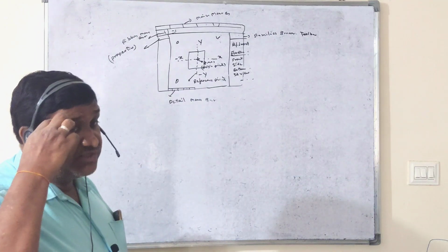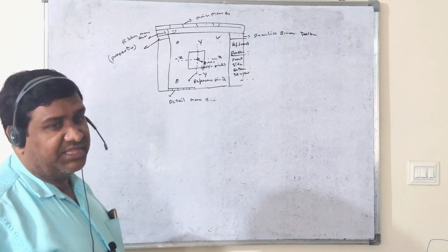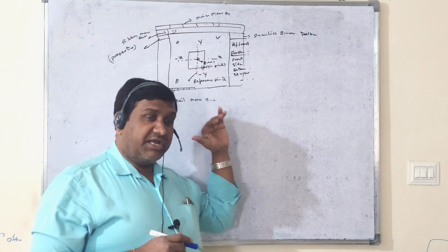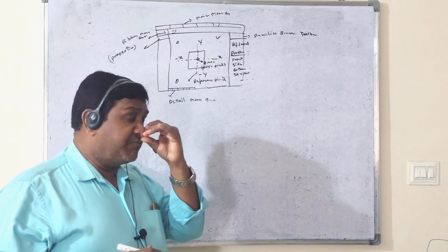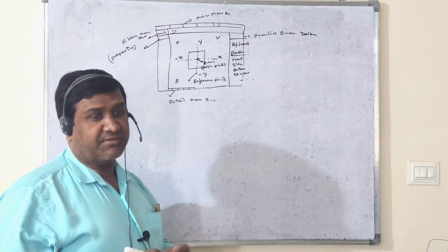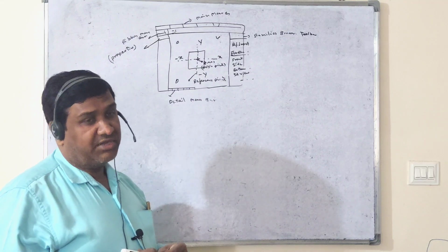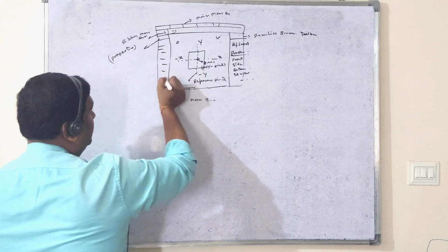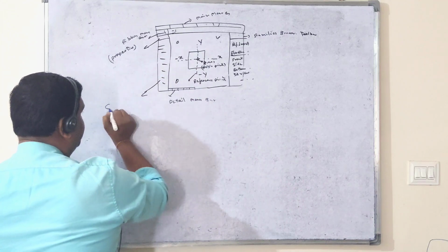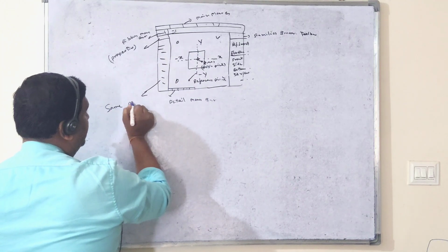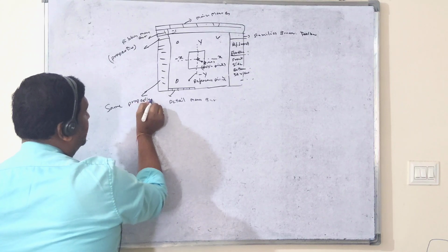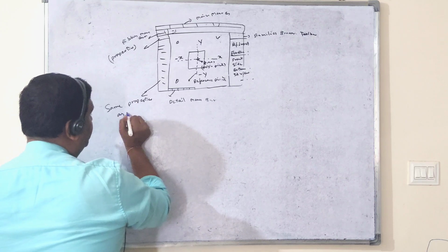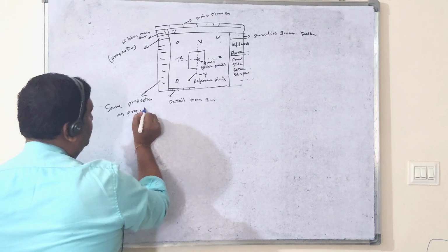There is no floor plan and no ceiling plan here. A ceiling level will be there, but no ceiling plan, because there is no creation of a floor here, only the creation of views. Those views we call reference planes, reference views, or reference levels. When you create any family, there are a number of properties, the same properties as in the project browser, because the scaling and the detail view will be here too.